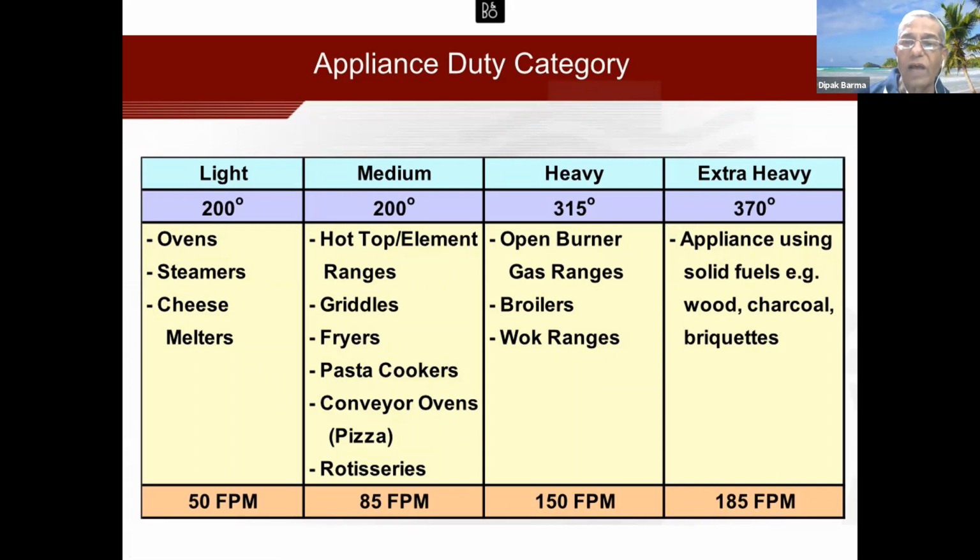We have had one experience where I was not told what the requirement was, but they started making Chinese food. They put noodles in water and then pick them out of the water straight off and throw them into huge vessels containing oil. So it actually gives out a sudden burst of steam and effluent around. So unless you know fully well what is required to be done, you have to have the hood and the velocities decided accordingly.